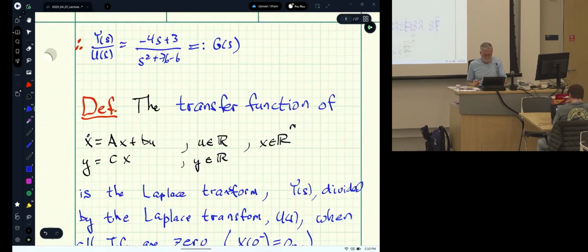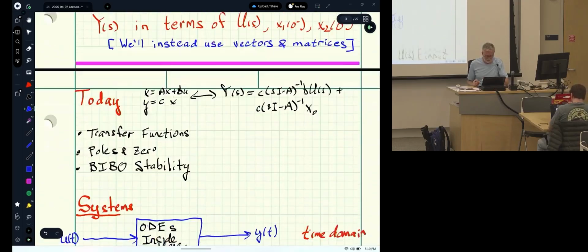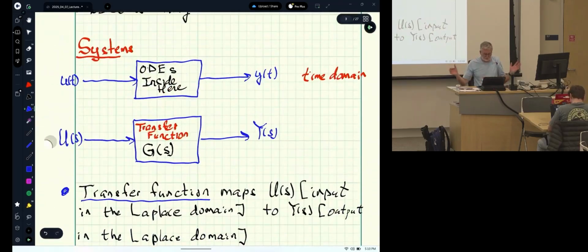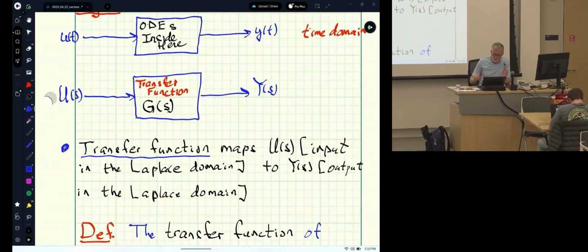Okay. Whoops, where's my systems? Okay, so differential equations, we have input output, so just y and its derivatives equals u and its derivatives, linear combinations. Then we just write down the transfer function by inspection. We have a state variable model, x dot equals Ax plus Bu, y equals Cx. A little more complicated algebra, so we use software to do it.